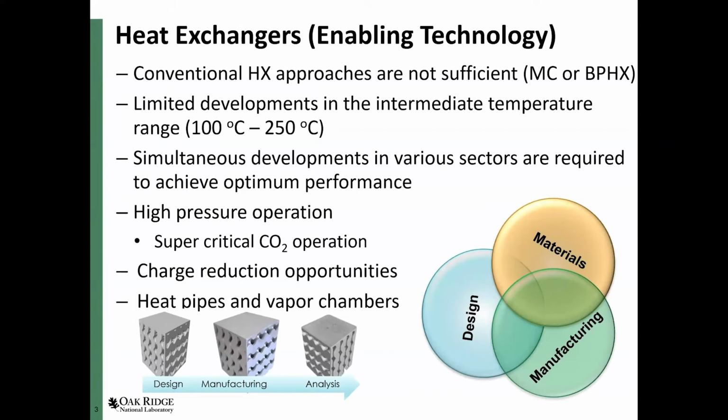So the very first thing which comes to mind when we talk about the high temperature heat pumps, or in general, any waste heat recovery process, is that heat exchangers are essentially one of the key components which must be considered when it comes to the design of the overall system. There have been obviously a lot of efforts in the design of microchannel and brazed plate heat exchangers, which are much more compact and efficient compared to the conventional technologies. However, when we start looking at, I'll call it, the intermediate temperature range, because that's a relative term, that is an area where there is still a lot of potential and further developments are required.